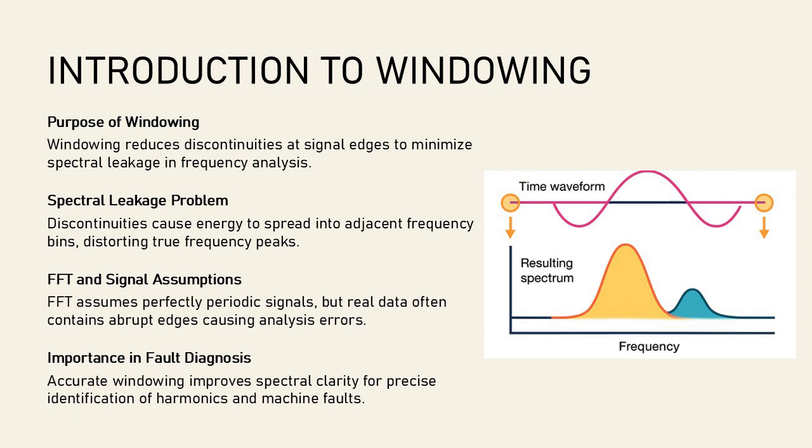Without windowing, the spectrum may show smeared peaks and false frequency components, which can mislead analysts during fault diagnosis. Therefore, windowing is essential for achieving clarity and precision in spectral analysis, especially when dealing with complex machinery signals where accurate identification of harmonics, sidebands, and fault frequencies is critical.